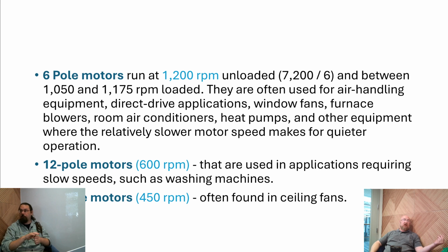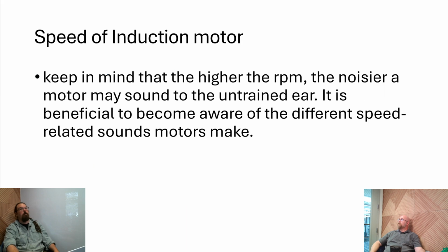You can get away with much smaller windings, and for that application it can actually be much more energy efficient to use a 16-pole motor rather than a 2-pole. So keep this concept in mind: frequency has a direct correlation to speed with every induction motor that exists.